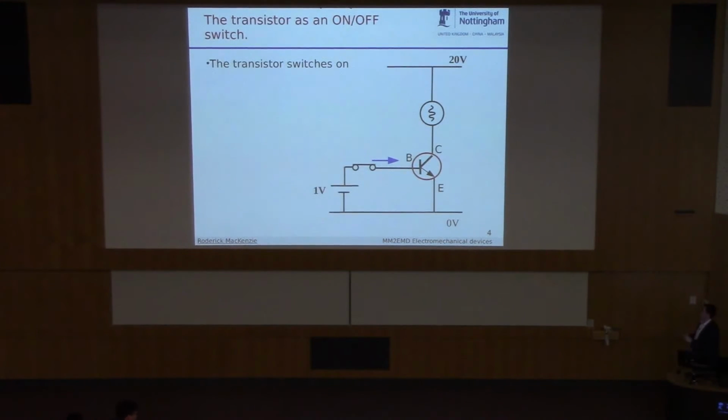I then said we can use a transistor for that, and transistors are really cheap, really small, and they don't draw much power. So in portable devices, you want to be using transistors to switch things on and off rather than relays. They've also got lots of other advantages, like they're quick, whereas relays are mechanical devices, therefore slow, etc.